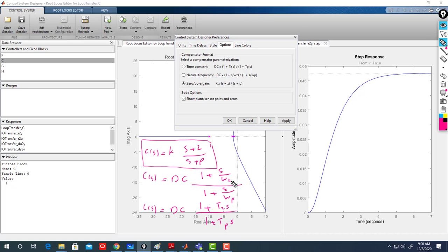If you want to convert from this to this one, you take Z here, so you get (1/Z)s + 1 form. If you take P here, so 1 over (P s + 1). Then K times Z over P is the DC gain, and 1 over Z is omega_z. So this becomes your frequency.